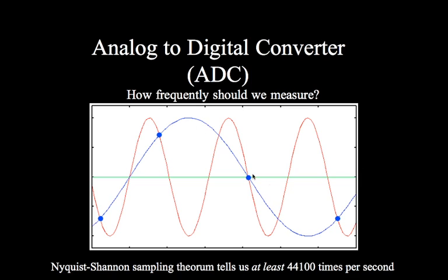And all of a sudden, we have a sound that is within the range of human hearing. Okay? So, in other words, if we top off the sample rate just above the range of human hearing, there will be digital artifacts that will be transposed into the range of human hearing. So, again, this red sound would be something too high for us to hear, something that a bat would hear. But what the computer will hear will be this new sound that doesn't actually exist.